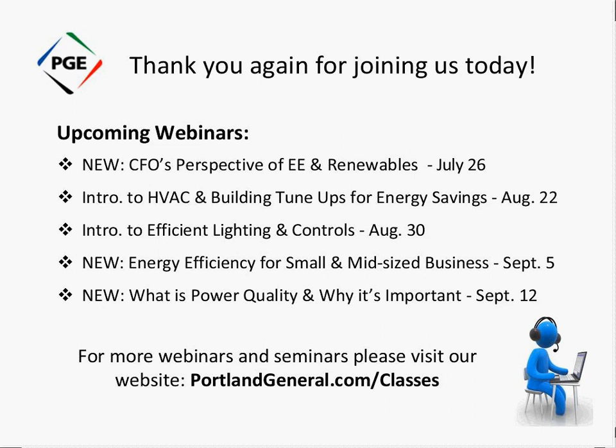It also is a way to allocate some of those capital costs to the customers that have higher demand rather than customers that have lower demand. So kW is the measure of demand. kWh is the measure of energy. Demand would be about 10% or less. If it's more than 10%, you definitely need to call somebody. It means you have some unique operations or something going on that is out of line with typical business operations.